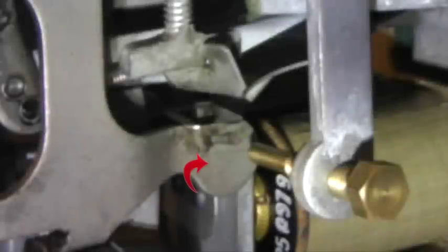This is the head of the double dog. On top of the head is a tooth, over which the release link is latched. Whenever the release link is latched over the tooth, the double dog is prevented from engaging the ratchet teeth. It is unlatched on the first vertical step of the shaft by the operation of the vertical armature, and the double dog is freed up to rotate forward.